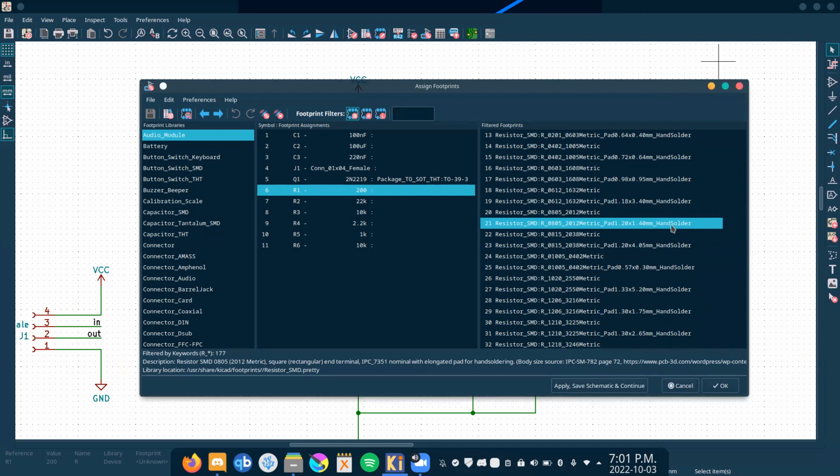Do we actually solder on surface mount resistors? We don't just pay to have that done with the PCB? No, we're free labor. Some places do it cheap. I would actually like to do some reflow, but on the last rocket, we soldered everything by hand. It's honestly not too bad, unless your PCBs are getting really complicated with a ton of components. 0805 is probably the smallest you want to go, unless you're doing a more advanced design. 0603s are solderable, but they get painful. Soldering 0201, that'll never happen. You've got to have steady hands.